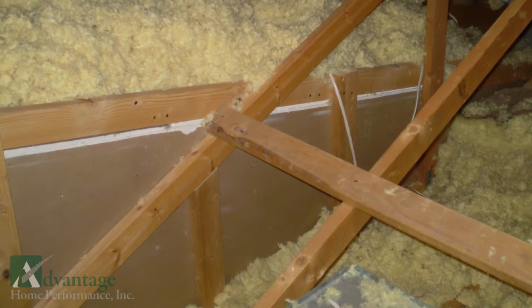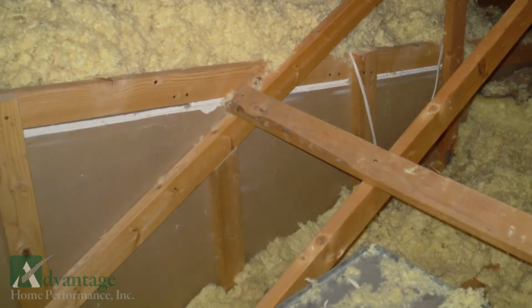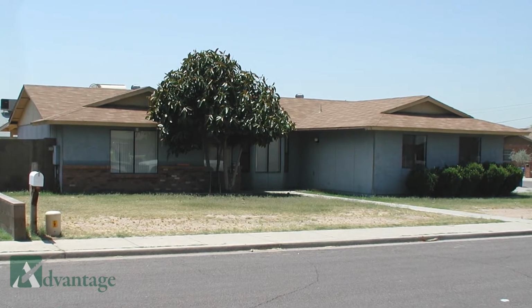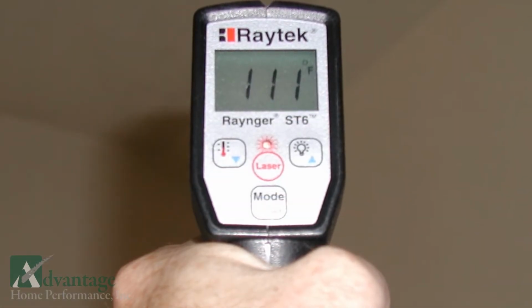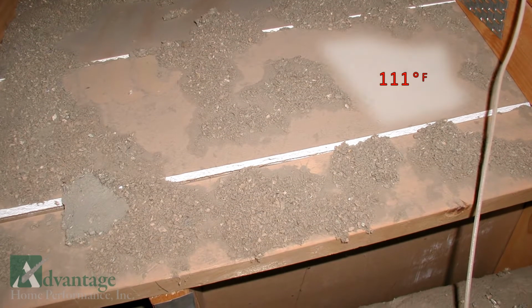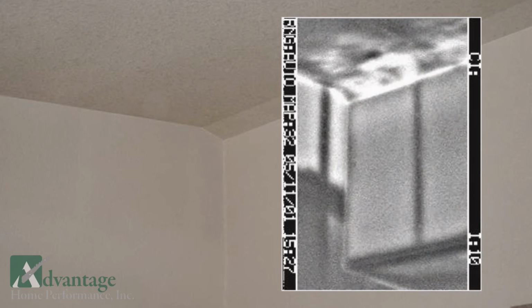This is an uninsulated wall between the house and the attic. Notice the bare sheetrock with an R value of less than 1. Missing insulation can have a profound impact on a home's comfort and utility bills. This house in Mesa has a ceiling temperature of 111 degrees Fahrenheit at 12:30 in the afternoon. As seen from the attic, this area has almost no blown insulation and uninsulated knee walls. The same ceiling as seen through our infrared camera. In this image, white is warm and shows heat radiating into this living room.